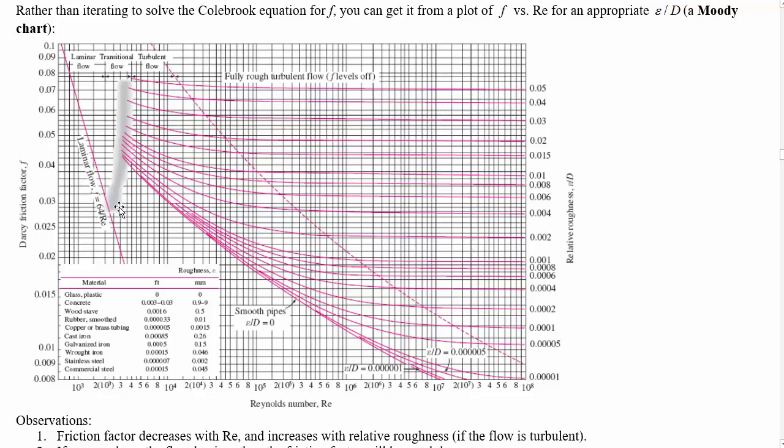On another extreme, if we're in the laminar flow regime, then because friction factor goes like 64 divided by the Reynolds number, you can see that the friction factors for laminar flows, where they line up with the turbulent ones, end up being a lot lower, especially at these high Reynolds numbers here. So if you can somehow maybe use laboratory smoothness conditions on the walls of the pipe, then you can maintain a lot less head loss for flow in that pipe than you would normally get if it would kick into turbulence like normal.